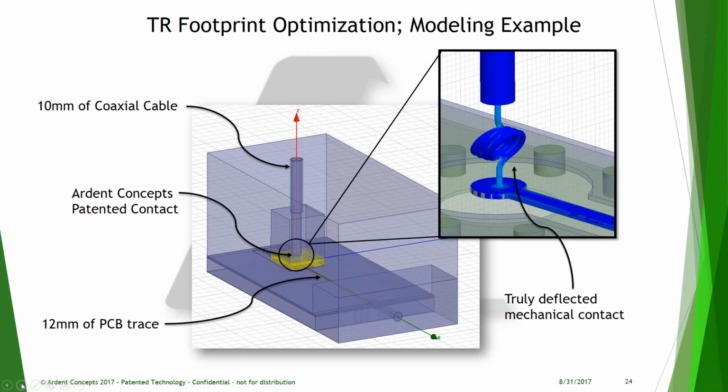Now, other people have approached and said, instead of an S2P file, can I just set my wave port at the capture pad? Well, right away, I see a problem with that, because if you look at the microstrip launch, I don't see how you're going to set a wave port there. Usually a wave port is designed as a coaxial structure, and the ground of that coaxial structure would short out right on that narrow trace right there.